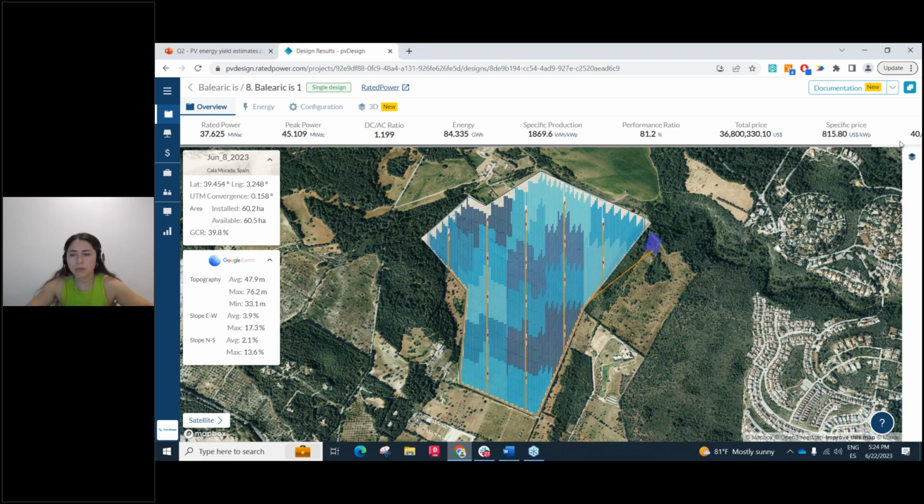So we have another question, which is: what is the most commonly used p-value to assess a PV plant construction permit and secure funding? Okay, so if we are talking about financial evaluation, P90. Investors often rely on the P90 estimates to evaluate the financial viability of solar projects.